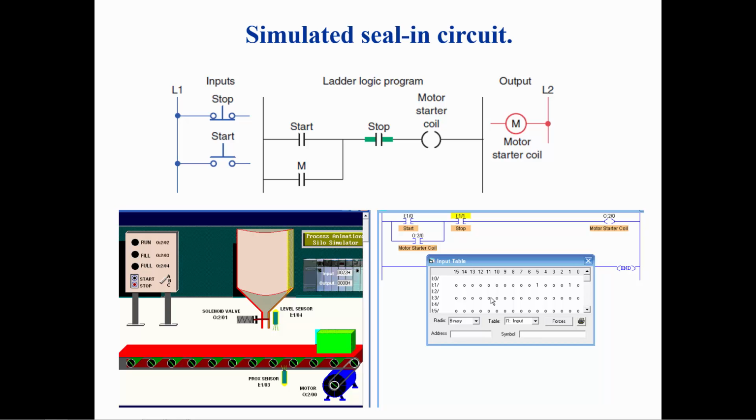When the start push button is pushed, the motor starts the conveyor moving. The conveyor continues to move even after the start push button is released until the stop push button is pushed. Note that the contact addressed to the start push button, I:1/0, is only true momentarily.